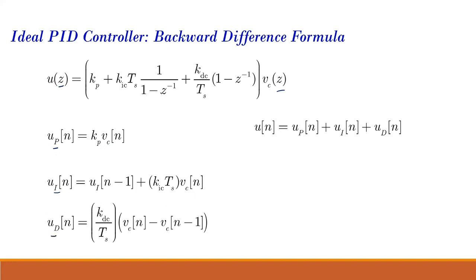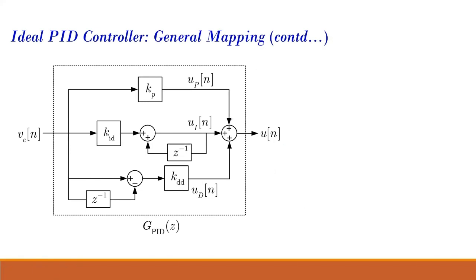So this is how the PID controller has to be implemented in my FPGA, my microcontroller, or any other digital platform which we are using to run this PID controller. When you write the code, you will write it in terms of these difference equations. When we show it in the form of a block diagram, this is my block diagram of a PID controller.